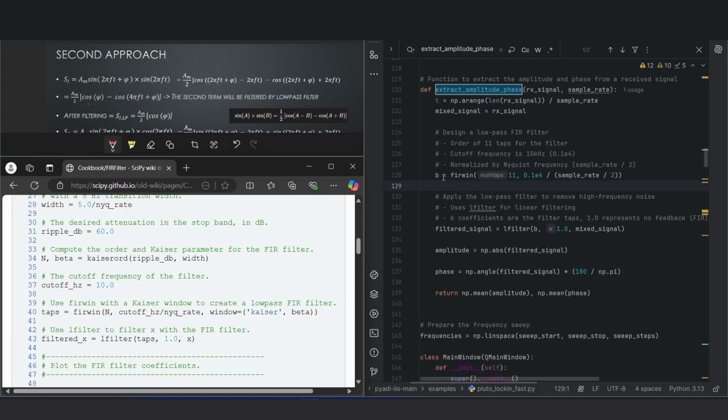After I have the coefficients for my FIR filter, which, as you know, only processes our X data and is not dependent on our previous filter output data, which are the output of the low pass filter, or Y. So basically, after I have the coefficients, I use lfilter, I just give the coefficient B to it, and because we are FIR, we just set the denominator here to 1 and then pass the main signal to it.